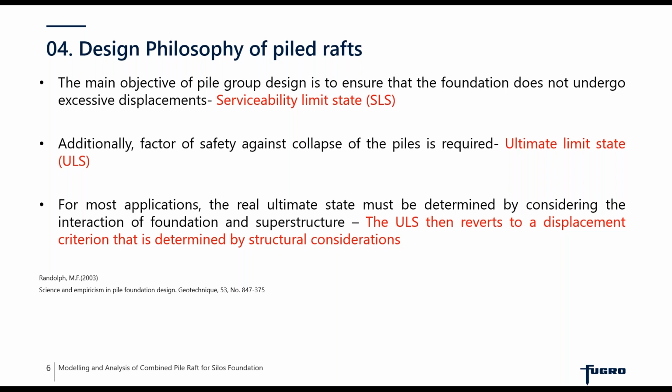Now, for most applications, even the ultimate state is determined by considering the interaction of the foundation and the superstructure. And it turns out that the displacement criteria is what governs after considering the structural considerations.